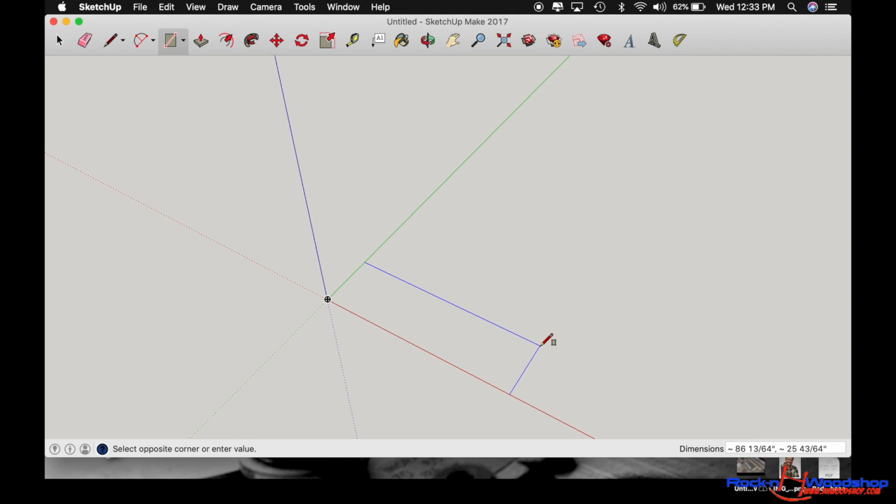Now we can't establish height yet because it only works in a two-dimensional format until we push and pull it in the directions that we want. And you'll see that in just a minute. So let's make a 2 by 2 inch square. While this is being dragged around, all you got to do is on your keyboard type 2, comma 2. The comma separates the two measurements.